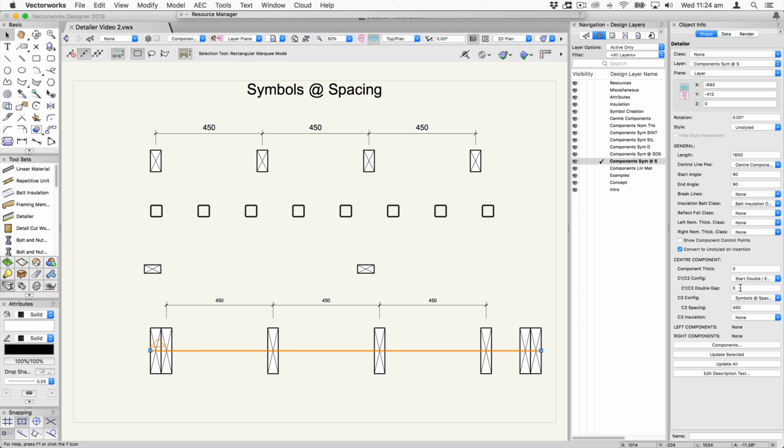And then you've got the ability to alter the gap between those. So typically it might be, these are 45 millimeter thick joists. So if I set that to 45, then I'm going to get that gap on here, and that will work if there's a wall sitting on top of this where you need to double them up. You can do that fairly easily. And as you drag this out, that double stud with that 45 millimeter spacing is going to be maintained at the end. And when this member here overlaps this one, it's going to drop that one out. So it's reasonably intelligent in that way.